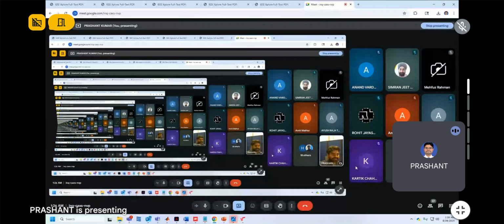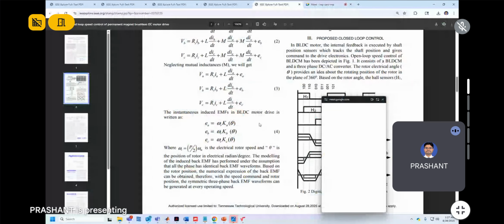There may be a chance that either of the Hall sensors may get damaged. Then the signals through which we were decoding the speed can give wrong information. We may not get exact information from the Hall sensor signals.